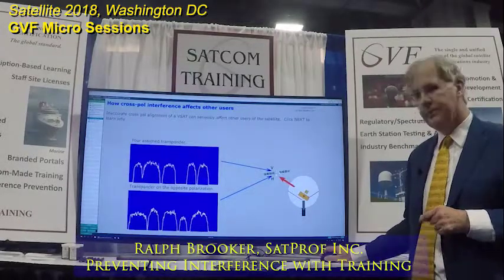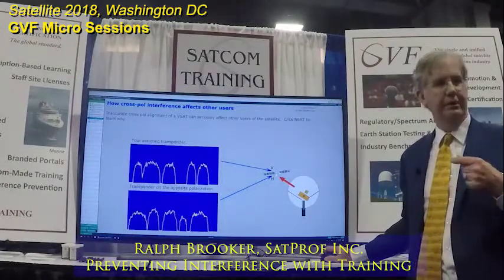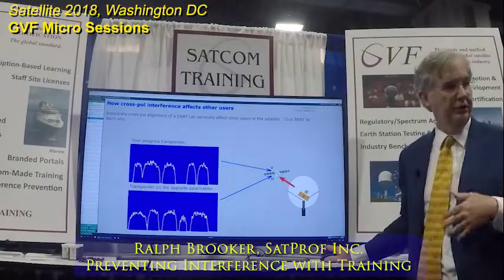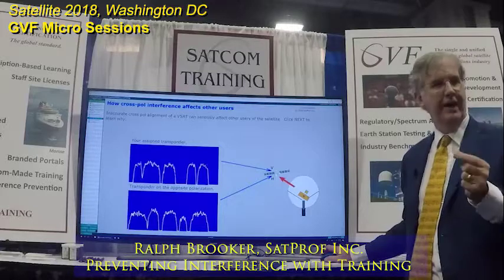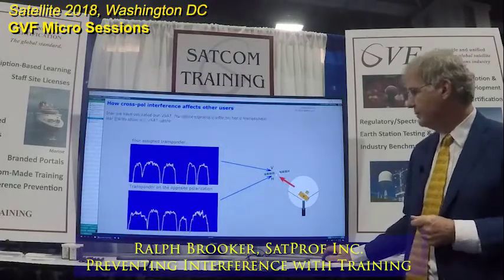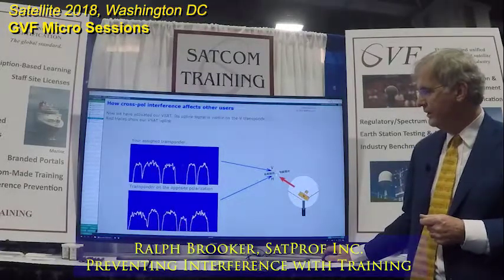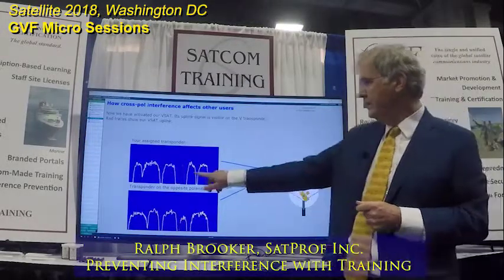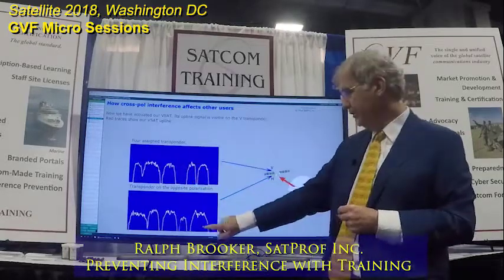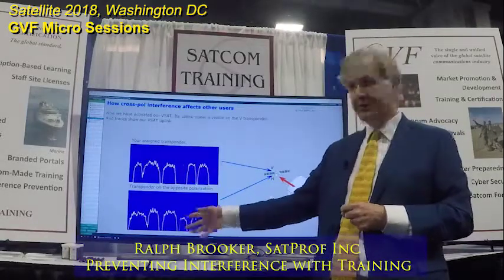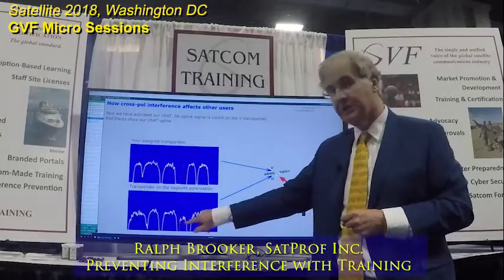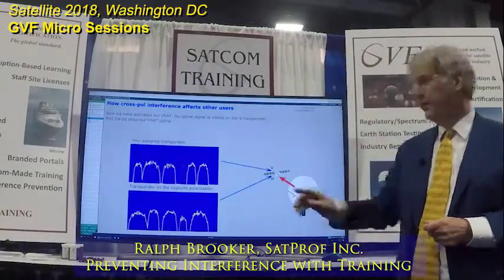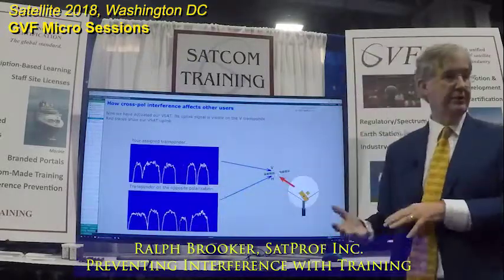And then for a fine adjustment, you have to really call and get feedback from the other end of the link. So usually that's done with calling the satellite operator. They find your carrier and read it back to you. So this is what happens if you don't have polarization set quite right when you're transmitting your carrier. This is the channel, the transponder you're supposed to be on. This is the transponder on the other polarization. This yellow signal here is somebody else's signal. So the red one is the same signal, but it shows up in the cross-pole transponder.